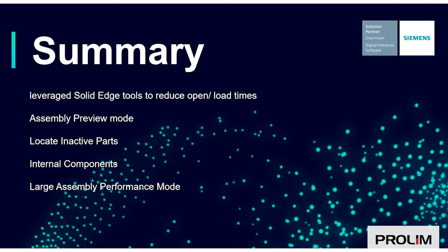So, in summary, we learned how to reduce open and load times of large assembly files by configuring the Solid Edge Assembly Open As options. We saw the small, medium, and large size files and how Solid Edge opens those. We saw how we can quickly and easily open large assembly files using the new preview mode. And being able to use the locate inactive parts command really helps us use that inactive part modeling data in the assembly to our advantage, speeding up our design time.